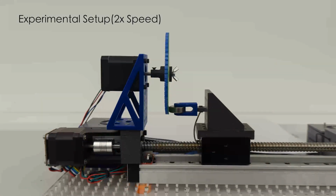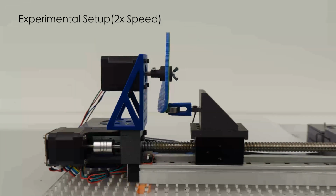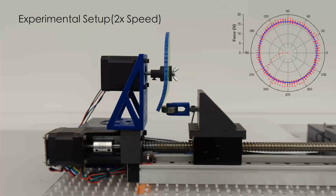In the first test, we use disc-shaped samples of 10 cm radius mounted onto a mandrel rotating at a constant angular velocity of 4.5 degrees per second. A simple force probe is used to impose constant displacement at the boundary of the sample. Readings from the force sensor are recorded continuously as the mandrel rotates, leading to a quasi-continuous force displacement plot.